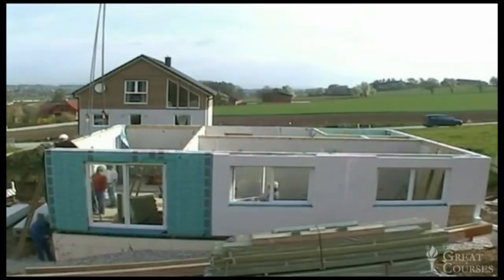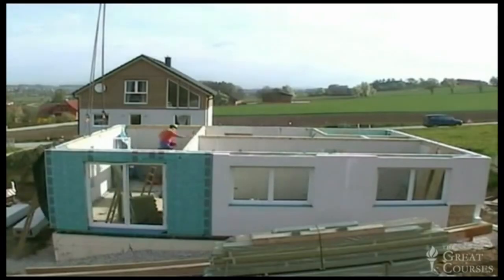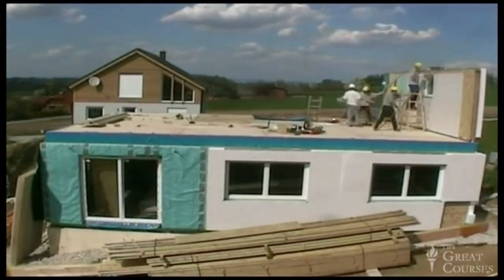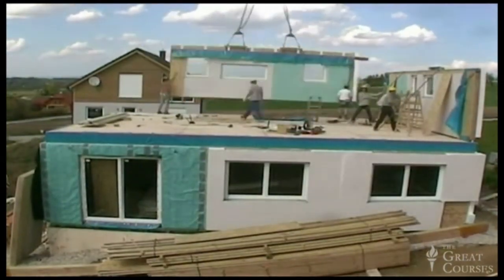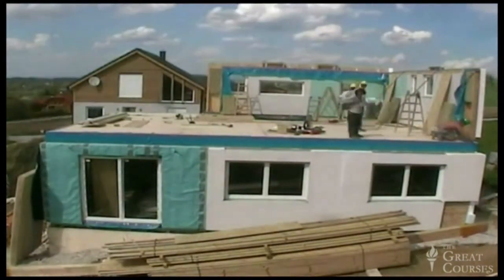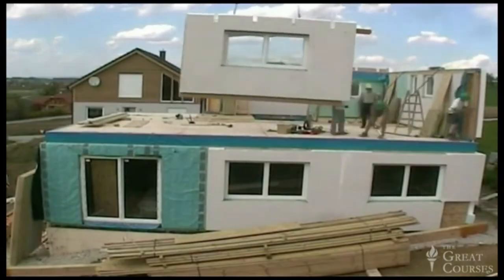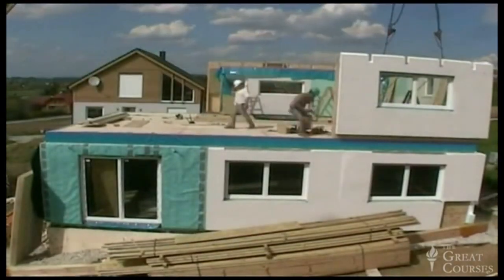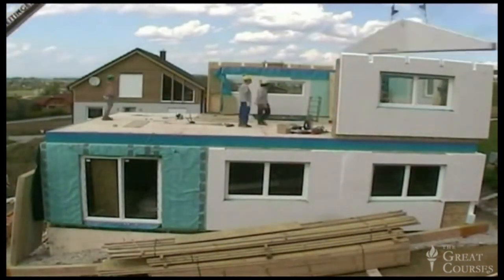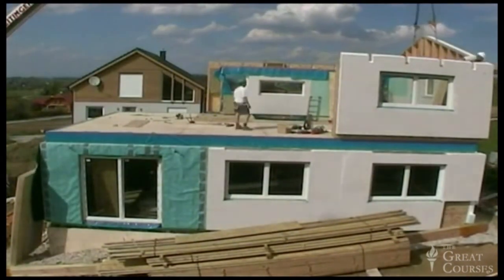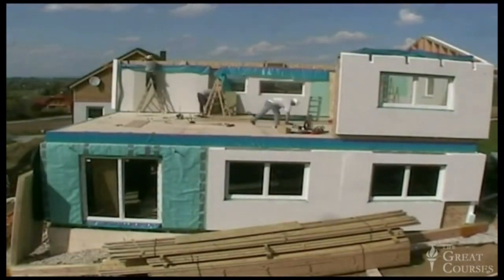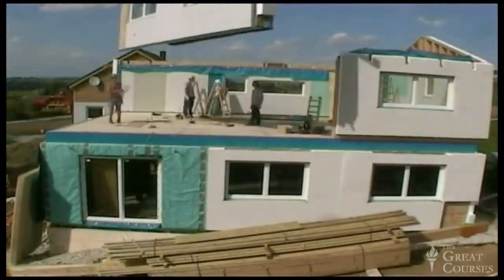Now, as you watch this time-lapse video of a SIP house under construction, I think you can glean some of this technology's amazing array of advantages. SIPs serve as both structure and insulation. They can be used for walls, roofs, and floors. Because they have so few joints, houses made of SIPs are considerably more airtight than their platform-framed neighbors. SIPs are always custom fabricated in the factory or shop, so on-site they can be erected quickly with a small crew and a crane. And as soon as this structural shell is up, the builders have a fully enclosed, insulated space in which to continue their work.